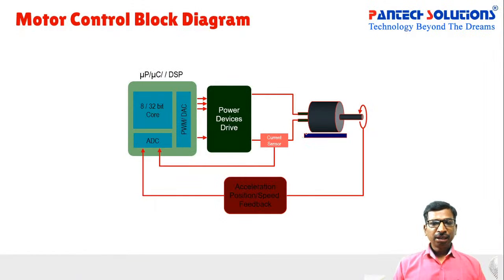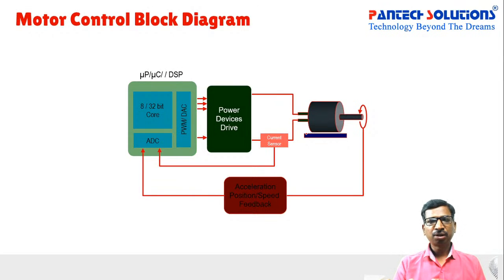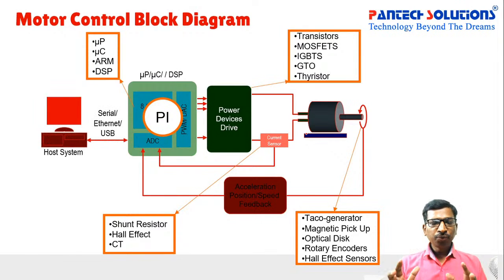And next thing, okay, you have controlled the motor, you have developed the algorithm, you have sensed everything, and you have perfectly developed the control algorithm. But you have to interface, or you have to take the data to the outside world, right? For that, you need a GUI, that is a graphical user interface setup. In this setup, the basic communication channels are UART, Ethernet, USB. Some additional protocols are also available, called CAN, LIN.